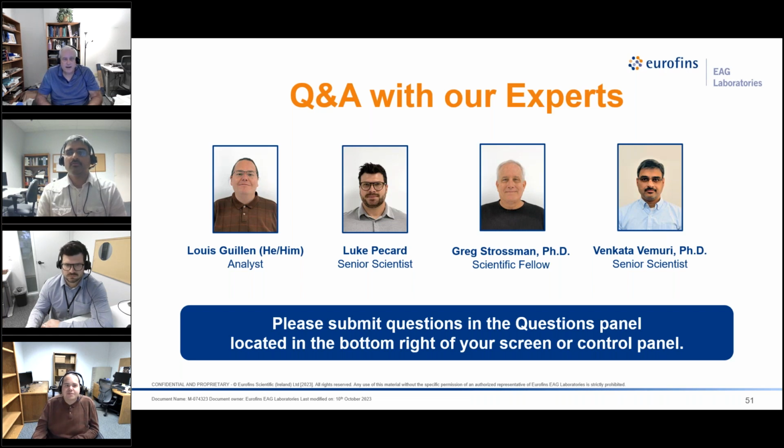So Luke, can XRF be used to identify formation of intermetallic layers in a stacked layer structure? Yeah, so as we discussed earlier, XRF can measure composition and thickness of the thin films, but unfortunately we can't identify intermetallic layers, mostly because it's just not segregated enough like we would find in thin film stacking.